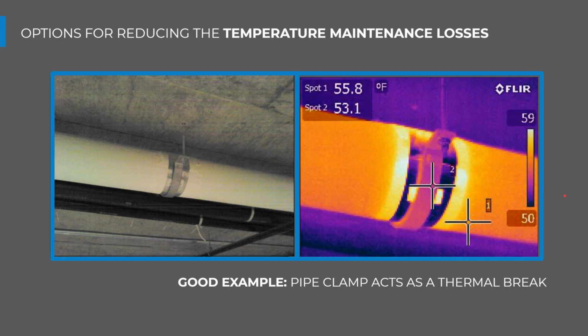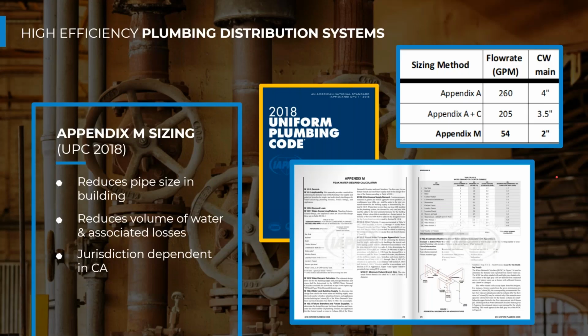They're standard products. It actually reduces the amount of time the plumbing insulators have to be present on the scene, which typically reduces first costs. The plumbing contractors install the piping with this certain pipe clamp support, and then the insulators can come back and just insulate up to that support rather than working around it, which was typically how it's been done in the past.